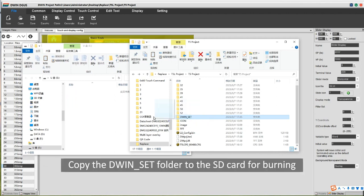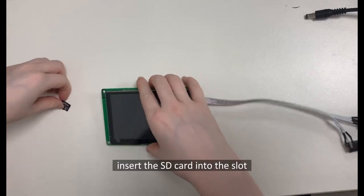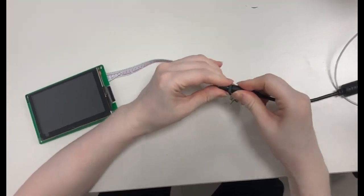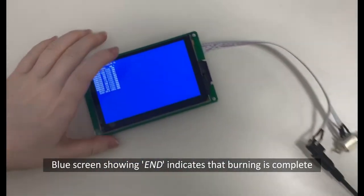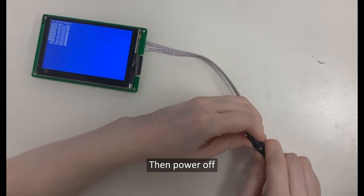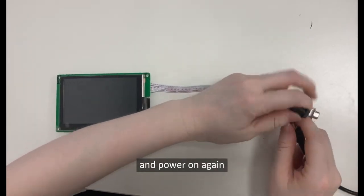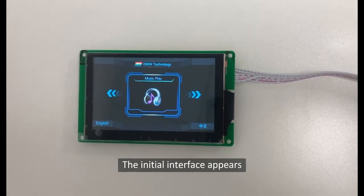Copy the DWIN set folder to the SD card for burning. Next, insert the SD card into the slot. And power up the screen. Burn the project to the screen. Blue screen showing end indicates that burning is complete. Then power off and remove the SD card. And power on again. The initial interface appears.